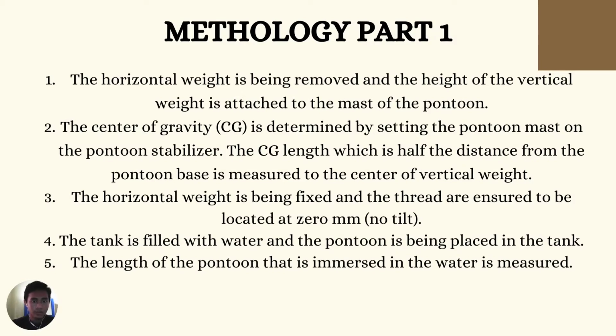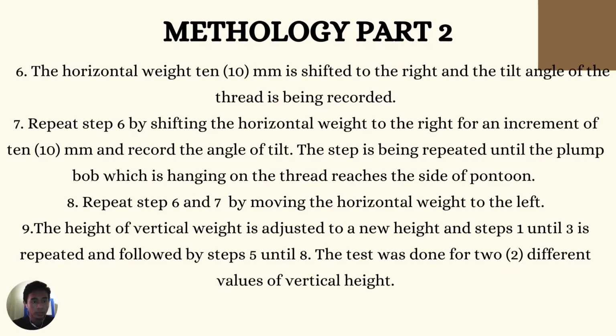The horizontal weight is being fixed, and we have to make sure the thread is located at the 0 mark, which is no tilt. Fourth, the tank is filled with water and the pontoon is placed in the tank. Fifth, measure the length of the pontoon that is immersed in the water.